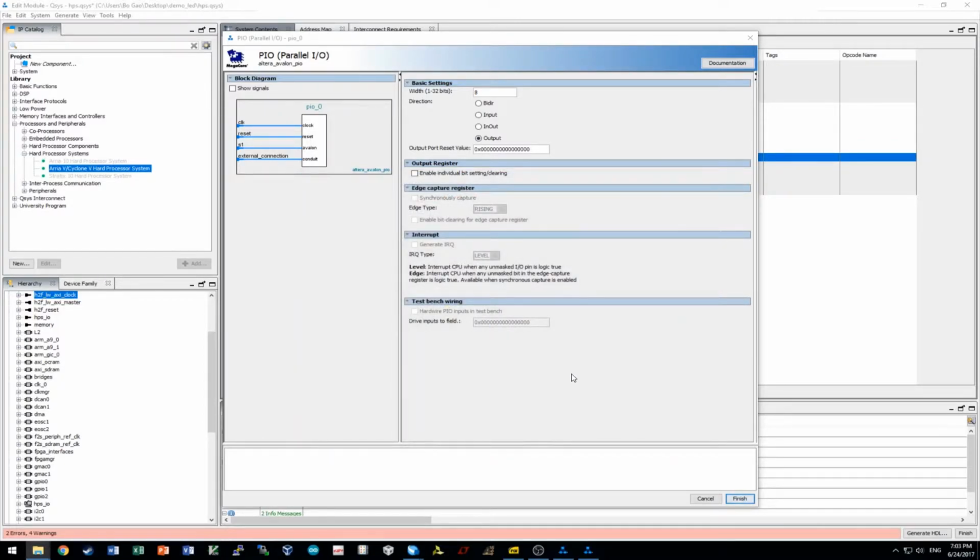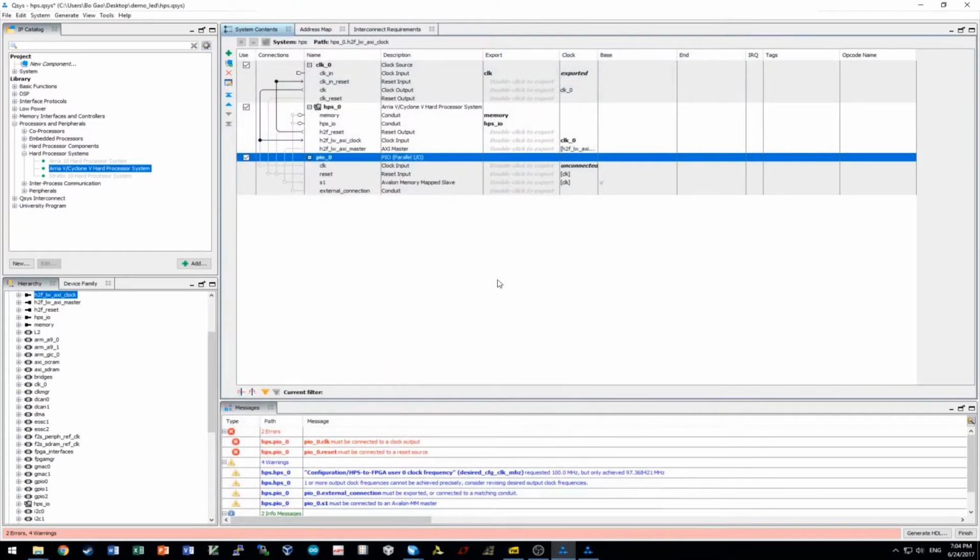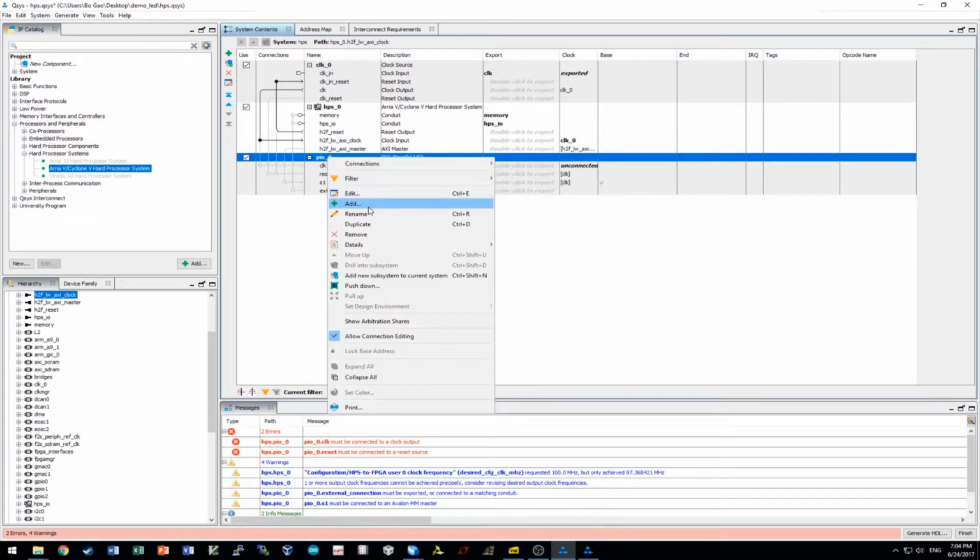But if you use another variable to store the status and you only write to this particular address, then it doesn't matter. So in this case, I will set output, and by default all the LEDs are off. The particular board is designed so that the LEDs are active high, so you set them to 0, they are all off. 8 bits output mode, and I think everything's set. We can finish. And we give it a more sensible name.